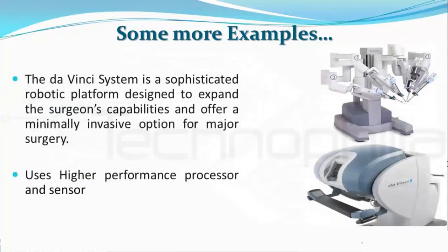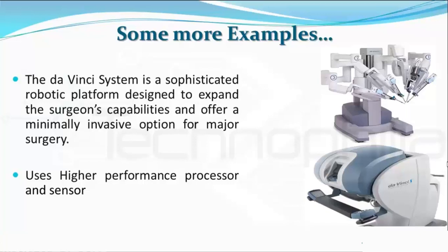Da Vinci, a telesurgical robot which performs open-heart surgery with great accuracy. It uses a telemanipulator, which is a remote manipulator, that allows the surgeon to perform the normal hand movements associated with the surgery, while the robotic arms carry out those movements using end effectors to perform the actual surgery on the patient. One of the great advantages of using this method is that the surgeon does not have to be present, but can be anywhere in the world, making remote surgery possible.